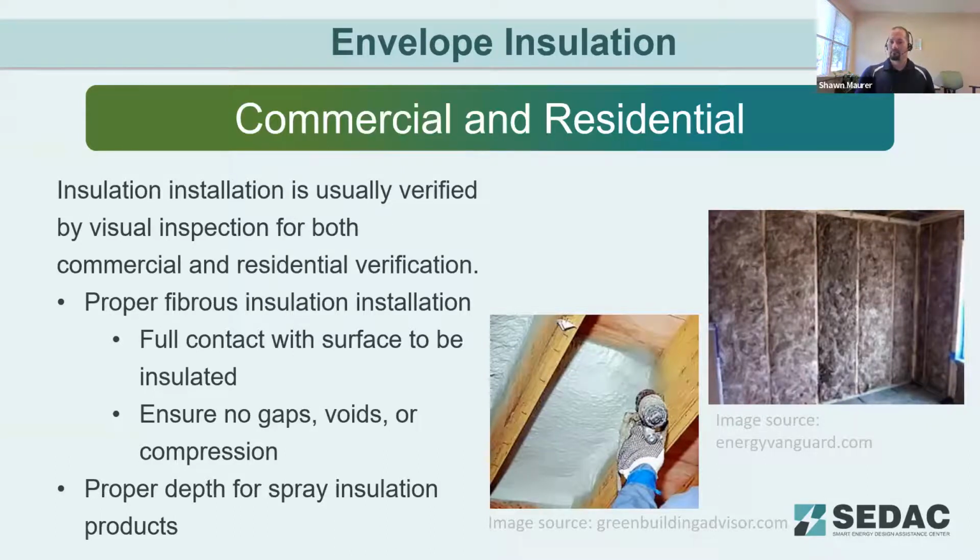Usually, again, for residential, as part of a rating process, a HERS rater will be able to do that inspection and submit that as part of a report to the code official. Code officials themselves may also do a spot check of insulation and just verify if these things are properly installed. Similarly, on the commercial side, there's the plan review. The inspector knows what types of insulation are going in place, and they go out on site for some of their inspections. They may either do a dedicated insulation inspection or maybe part of other inspections that they're doing. So they're going to just check and make sure that there aren't any obvious issues with the insulation work.